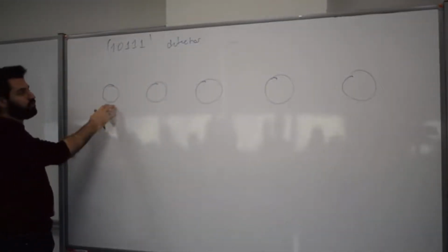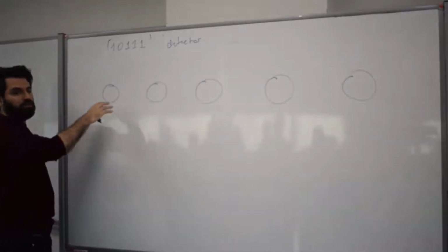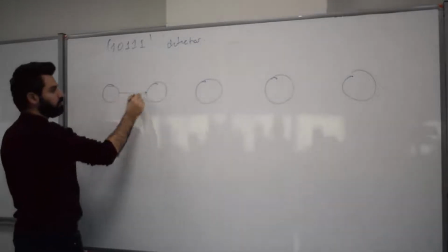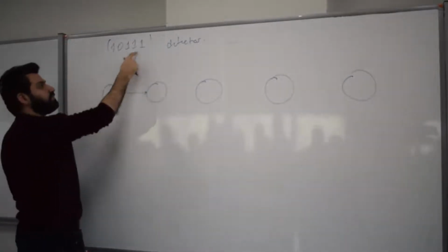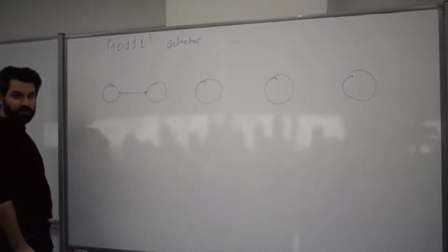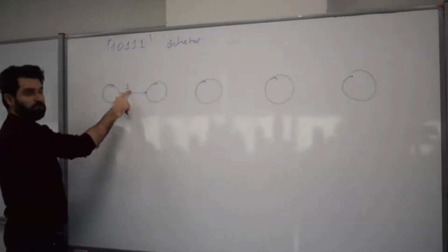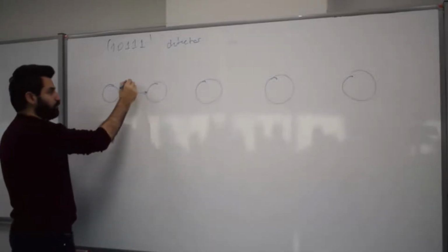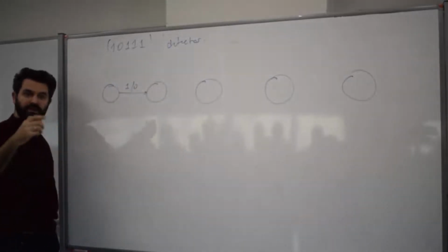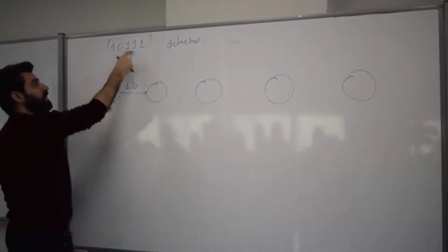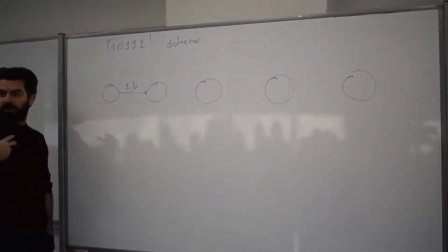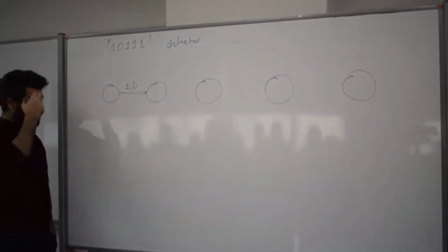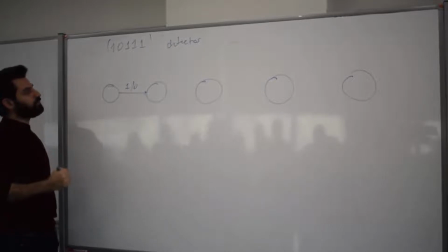So the first thing first, we have this detector, and as I said, one design approach to such a problem is to use the forward direction to encode this sequence. What does that mean? That means you can just make those transitions as you see these bits in the sequence that you would like to detect. For instance, 1 is going to cause you to move from this state to this state, and output would be 0. Because that means you basically started counting those bits or having them in your memory so that you can compare whether this sequence is detected or not, or accumulated or not in a given input bit stream.